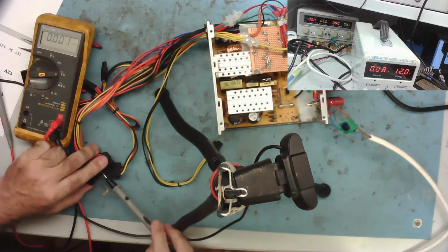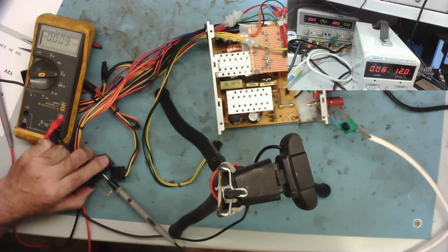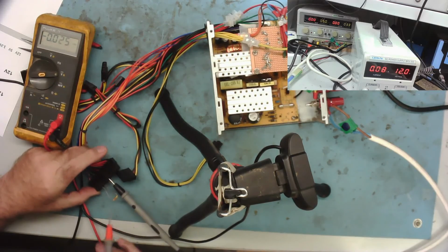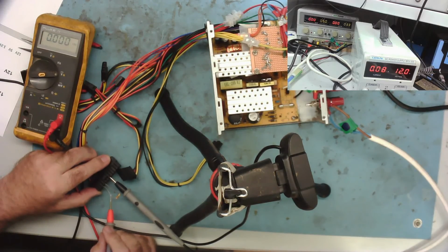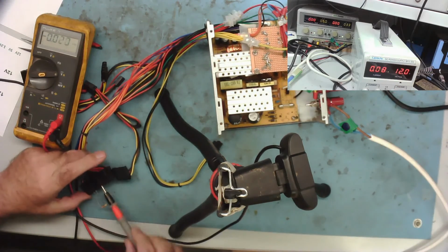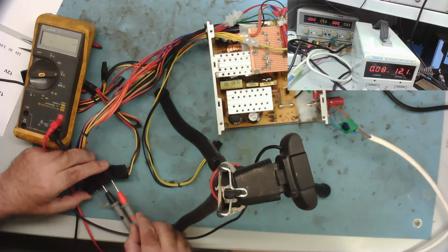Okay, so I've used one of my favourite things. It's actually a 22 ohm resistor, but it's low enough to ground it, and it's just a stiff bit of wire really. So we can now see the 0 volts on here. I know it's working because this now says 80 milliamps. So now we should hopefully have all the supplies coming through to here.